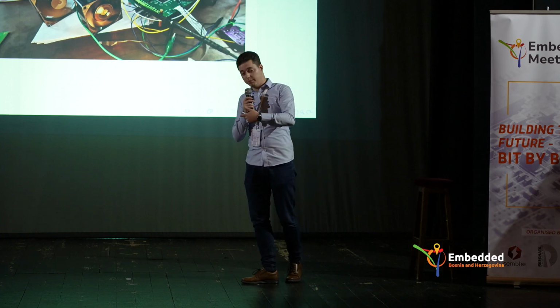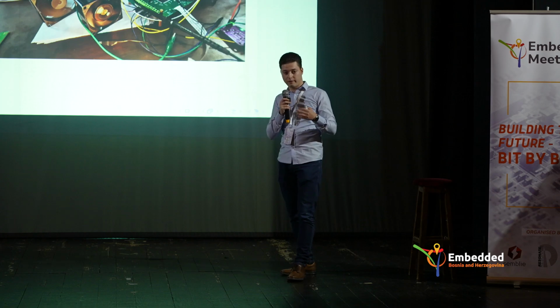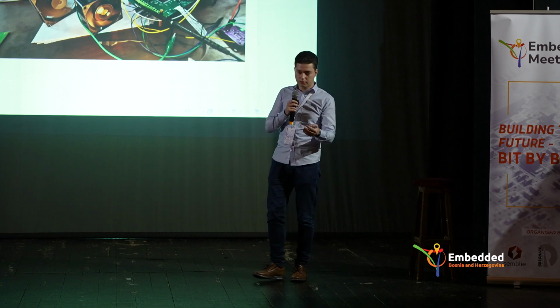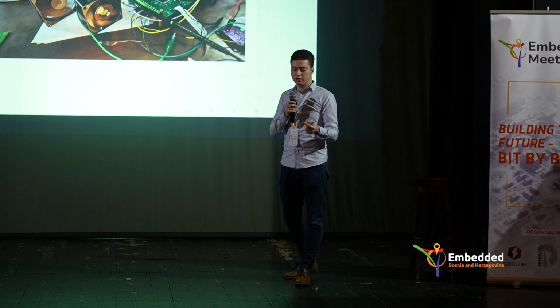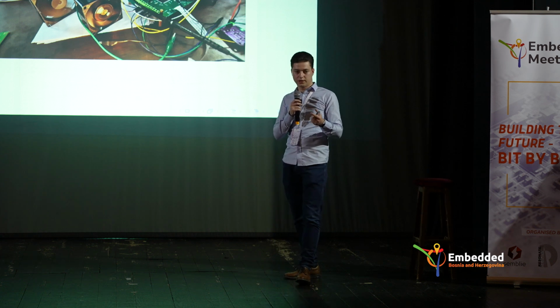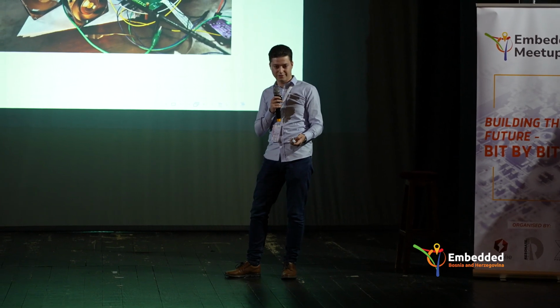The one thing I may have failed to mention is that we have the constant reallocation of addresses. That's why we use the SDRAM. We cannot just use one buffer. That's why we need double buffering, or we will be constrained by the image size itself, and thus the synchronization process itself will be misaligned, if that answers your question.